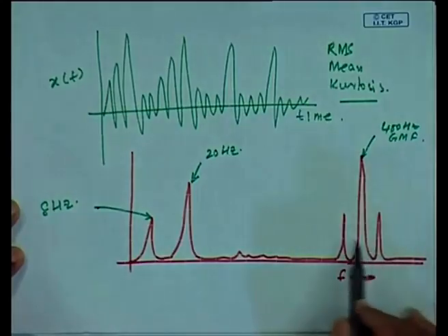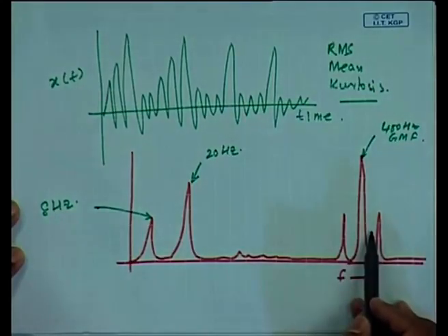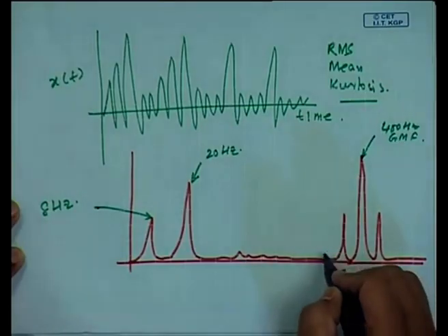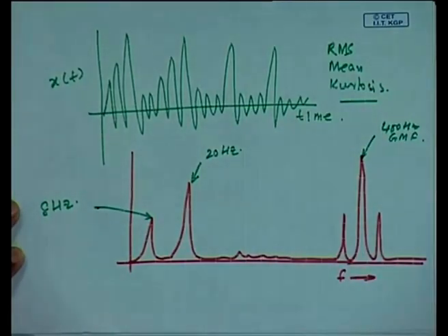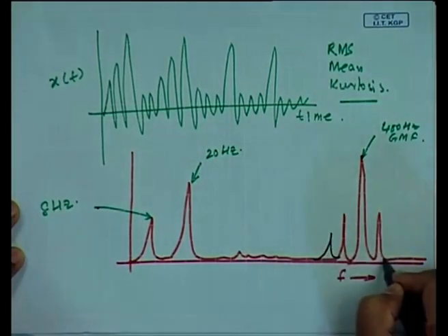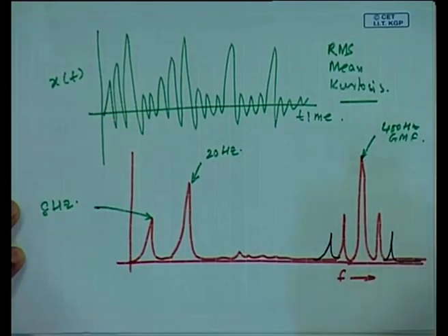But what I will also see is the side bands around the gear meshing frequencies, and I will draw another family here. Okay.